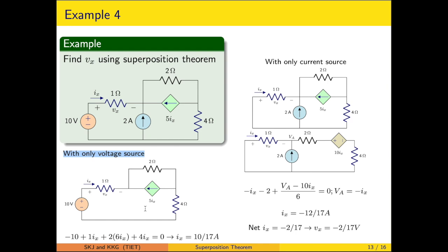So just to find out the equation, we have to have a KVL equation around this. So this is a current source, it is injecting 5Ix here, Ix is directed likewise. So the current through the 2 ohm resistor will be 6Ix with a polarity such that the left terminal will be positive, right will be negative, and so on.